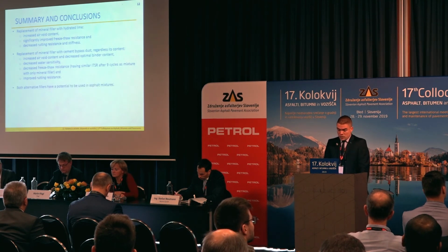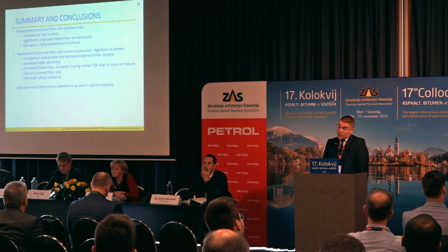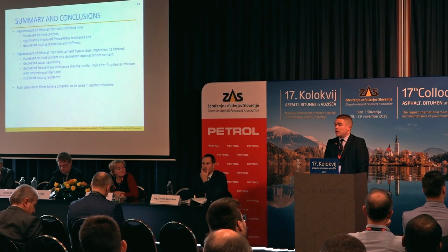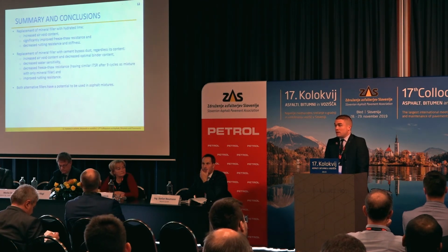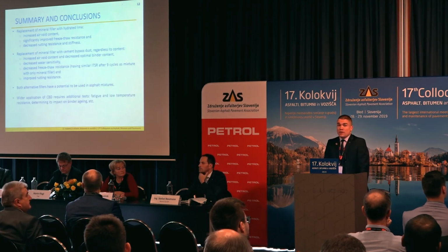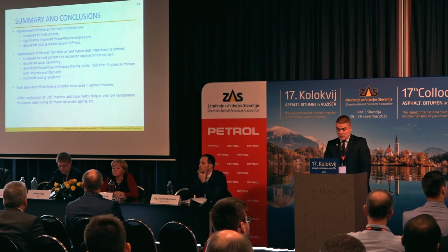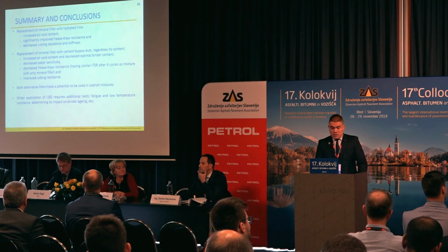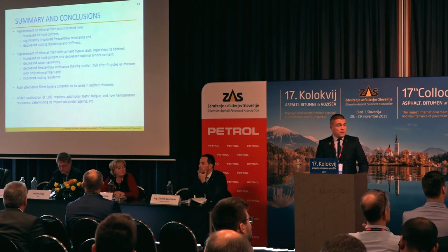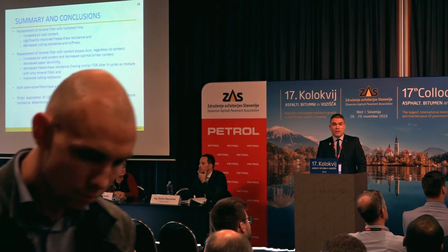So, the final conclusion can be that both fillers used in this study have a potential to be used in asphalt mixtures. As I said at the beginning, there have been many studies related to the use of hydrated lime in asphalt mixtures, but there are not so many related to the use of cement bypass dust. So, wider application of cement bypass dust requires additional tests, such as low temperature cracking, fatigue resistance, then determining its impact on binder aging, and etc.